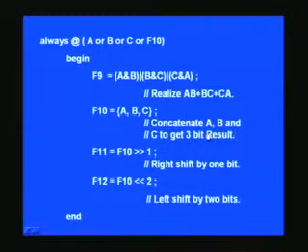Now, what we have seen over 2-3 pages, we have contained the entire thing in a single page here, the program as such. In fact, you recollect what we had done earlier is, we have realized the majority logic, which is AB plus BC plus CA. So note that ampersand stands for AND and vertical slash for OR, and that's how you get AB, BC plus CA. And this is precisely a part of program as such, Verilog code as such.